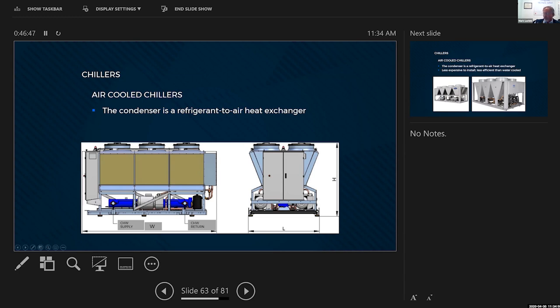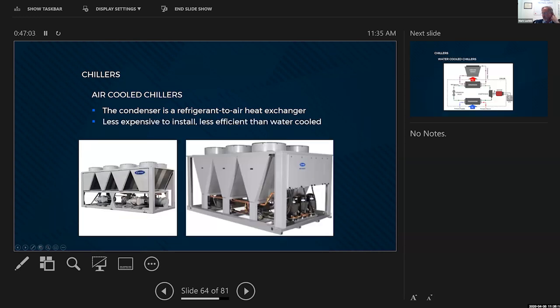Here you can see your evaporator bundles in blue, scroll compressor, and then the air-cooled condenser on top with coils on each side and fans on the top. Couple of real pictures. This one happens to have a pair of screw compressors on it. This one on the right has a series of, looks like 3 scrolls. So this is probably a 75-ton chiller.